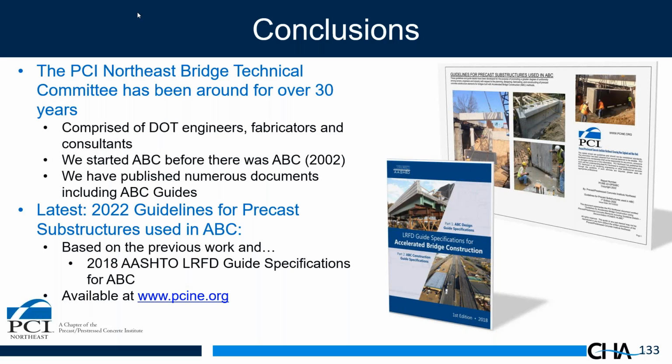And essentially, if the bars are still intact, the same procedures used to retrofit those connections after the earthquake would still be applicable. Again, other details we showed, the socket connections, where it really is the same as cast in place in the hinge zone. So the same retrofitting methods that have previously been used would be applicable to those as well. So that socket connection where the column is set into the footing and the concrete's cast around the column, the retrofit would be exactly the same as it would for cast in place.